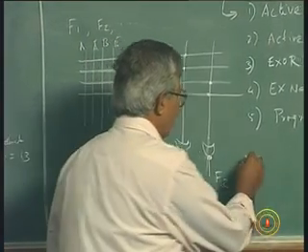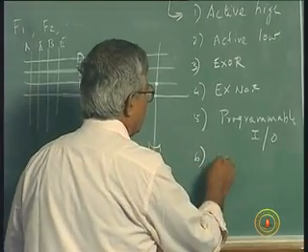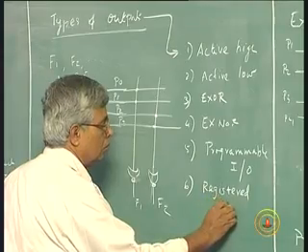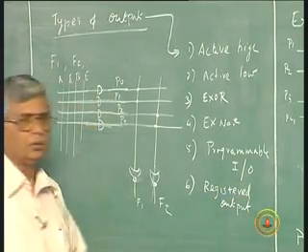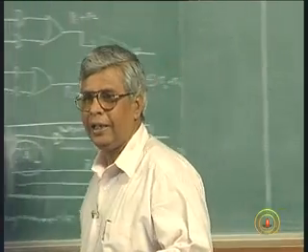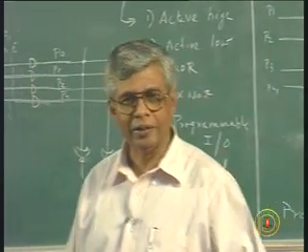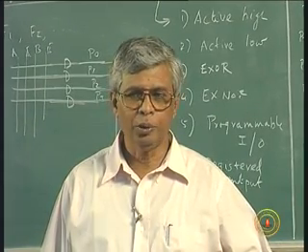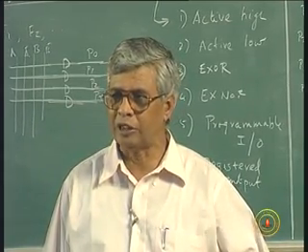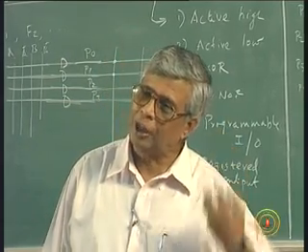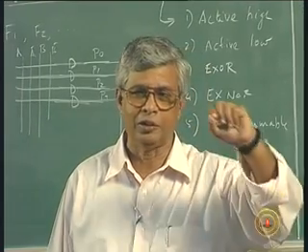And the last output is called registered output. Registered output is a combination logic used in a sequential circuit as a driving logic, as a steering logic. And what does it steer? Input of the flip flops, right? This is used as an input of the flip flop which steers the circuit from state to state. So, if I can also put that flip flop as a part of a PAL, I can finish my sequential circuit design in one single chip.